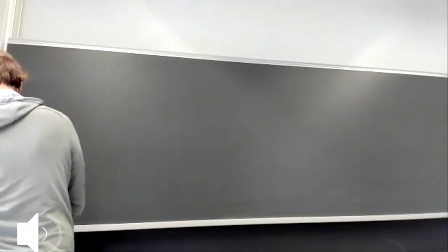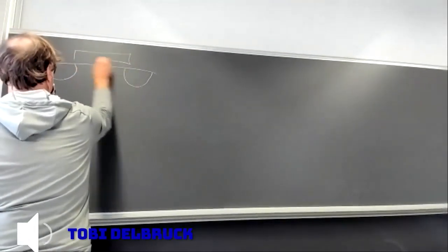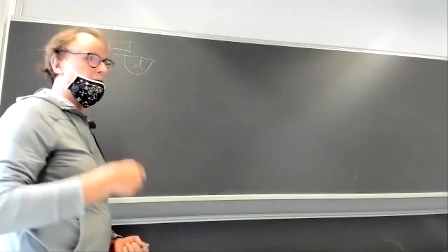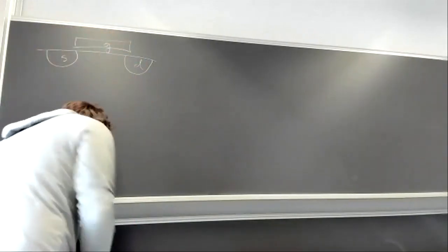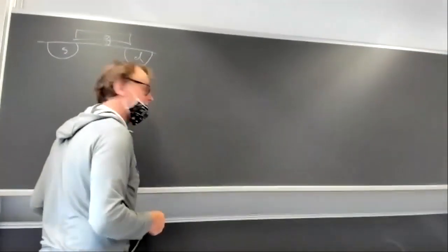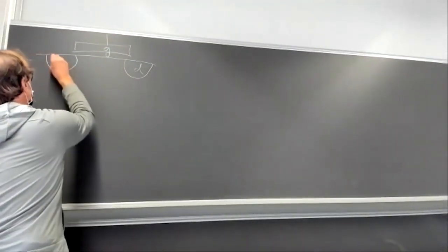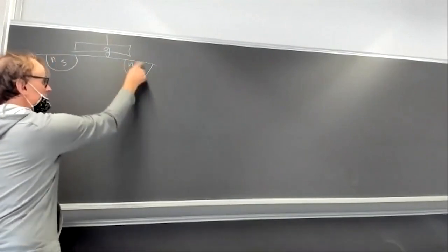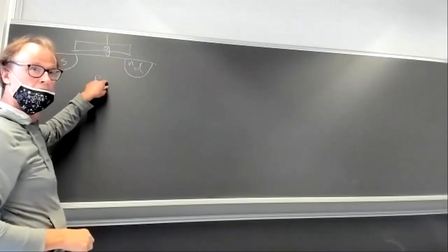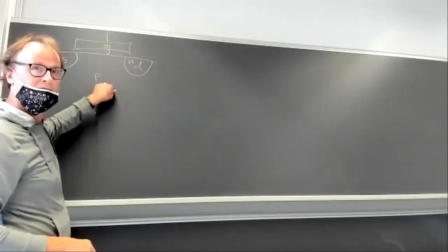Okay, so let's just draw the cross section of the transistor here. There's a source at one end, a drain at the other end. Above it is a gate. And the source is where the carriers come from, either electrons or holes, depending on the type of transistor. And the drain is where they fall out. So let's take the concrete case that is an N-type transistor. So it's doped with electron-rich stuff here, and then the substrate or the bulk of the transistor is p-doped. So it's rich with holes. So lots of electrons whizzing around here, lots of holes whizzing around here.